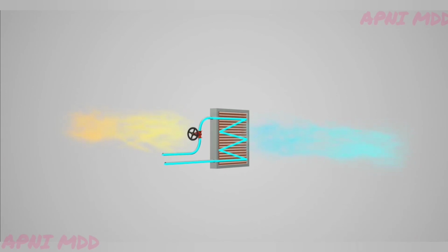At some point of time, the building space will be much colder and will require the valve on the cooling coil to be closed to maintain the desired temperature. So the cooling principle is, the cooling coil valve will be either opened or closed to maintain the temperature as required by the building occupant.